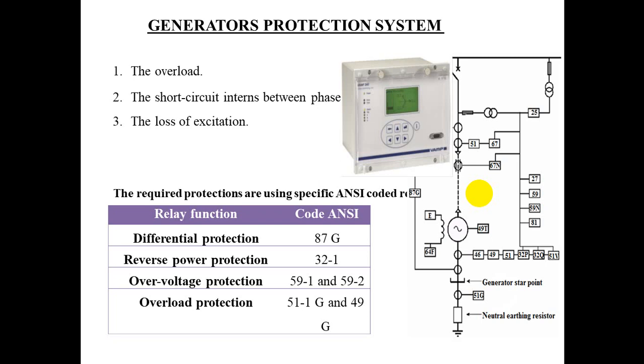In the case of smaller generators, normally below 30 megawatt, the generators are not equipped with embedded temperature coils but are usually fitted with a thermal relay, arranged to measure the current flowing in the stator winding.